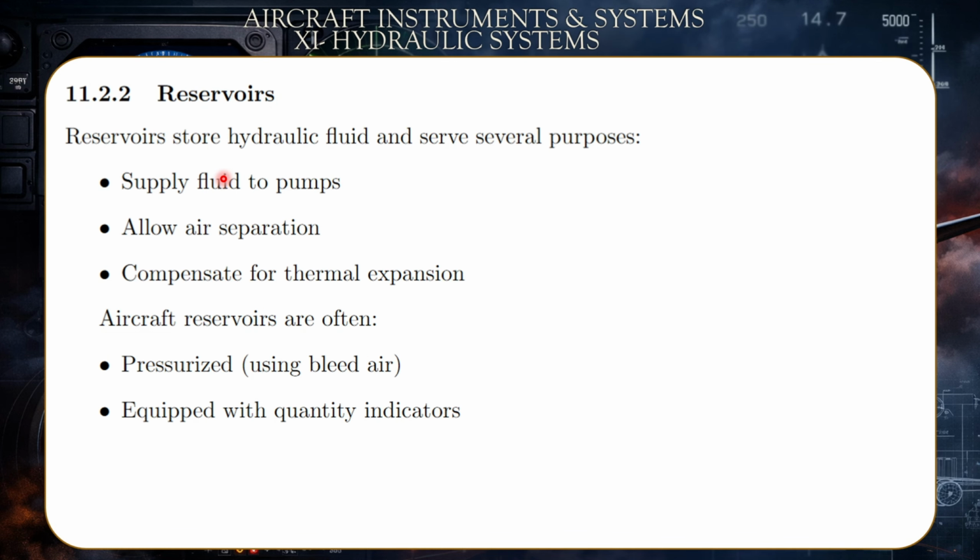Reservoirs. Reservoirs store hydraulic fluid and serve several purposes. First, supplying the fluid to the pumps, of course, allowing air separation so as to avoid the formation of air bubbles within the pipe system, which can stifle the transmission of the fluid pressure within the pipes, and compensate for thermal expansion, so that when you have thermal expansion, the fluid won't dilate, blowing up the pipes, or cracking them.